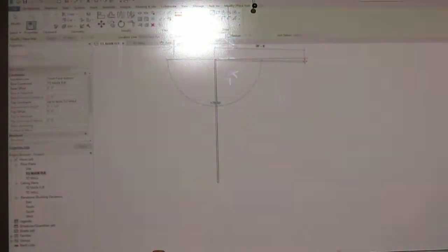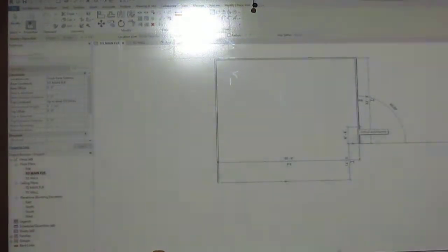If you press the shift key, it doesn't allow you to type anything. Right, you don't need to, just lock it in, just put your cursor in one direction. Click on the wall. Okay, and then go 56 feet. How do you go back? Just hit escape, select everything, delete. And then click on the architecture tab and it'll pull up your wall.